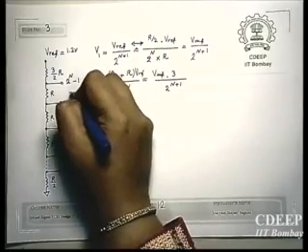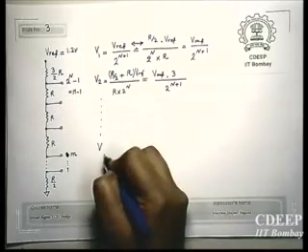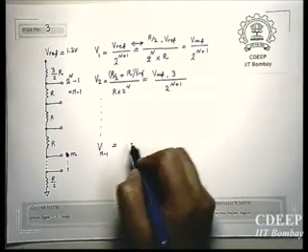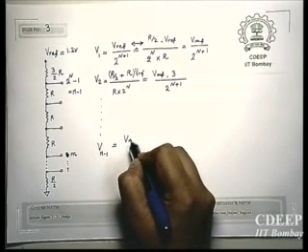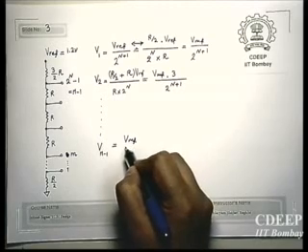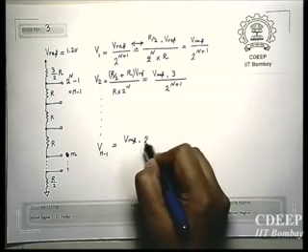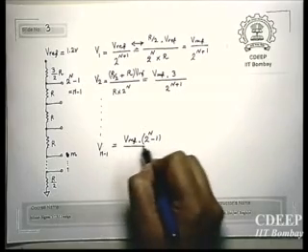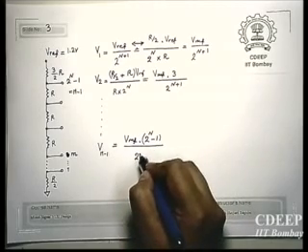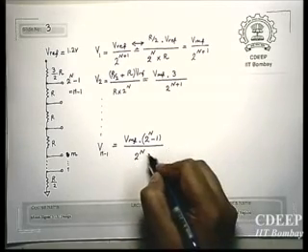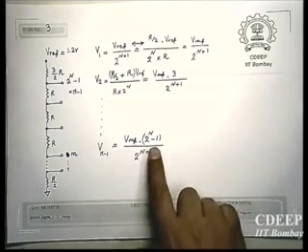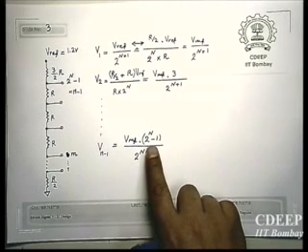I call it 2 to the power n, m. Okay, it will be easy: V1 up to Vm minus 1. We'll have all values. Eventually it will give you Vref into 2 to the power n minus 1 over 2 to the power n plus 1. Right? For example, for 3 bits, it should give you 7 by 8.